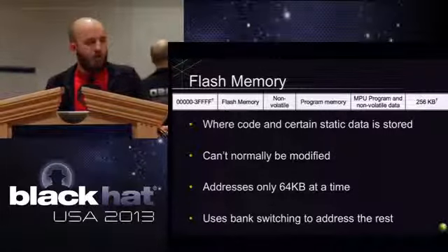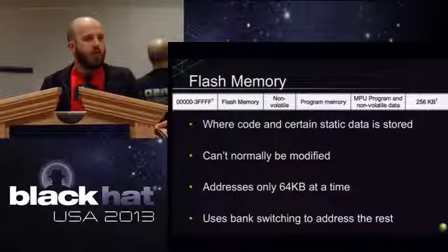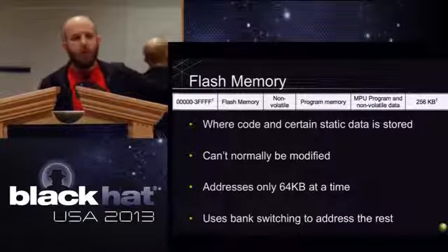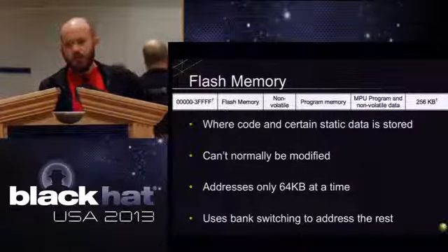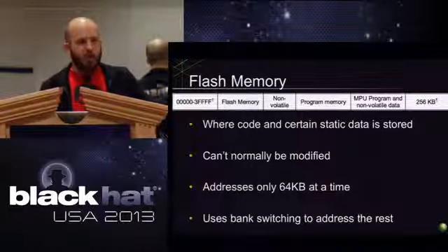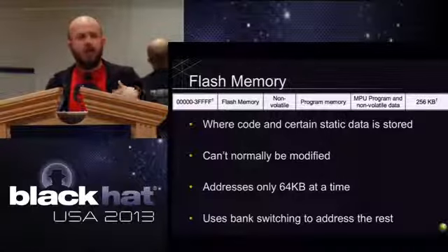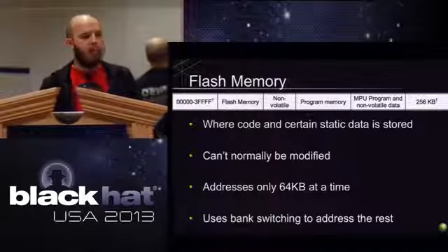Flash memory itself can't normally be modified. True Harvard would mean that this is read-only all the time. You would load code with a JTAG or whatever, send the production device out, and then it never gets modified ever. Now the reality is that nobody can do that. Nobody can ship code on a device and then never update that code again.